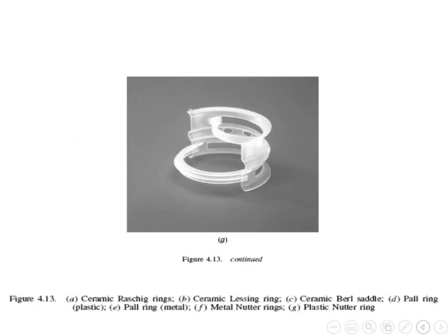So here I talked about three concepts: a relation between the bed height and the porosity, which we have done using the volume balance. Then we obtained a relation between the pressure drop delta P in the fluidized bed and L_mf, the height at minimum fluidization, and we got this using the force balance.